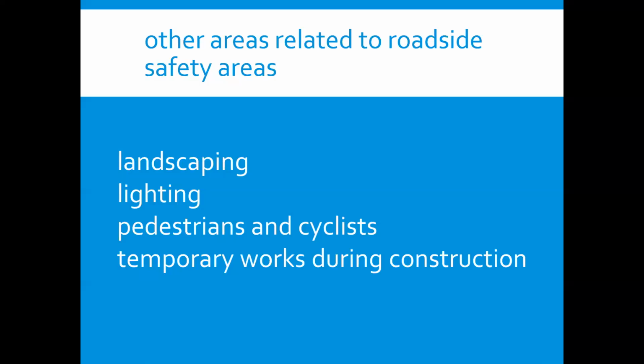Consideration should be given to the provision of exclusive bike lanes and to the treatment of termination of bike lanes. Pedestrian safety relates to a number of controlled crossing points and the provision of footpaths close to the traffic lanes. It is desirable for footpaths to be set back from the curbs to provide protection for pedestrians from errant vehicles. Local specific guidelines should be used to determine the provision of crossing facilities.